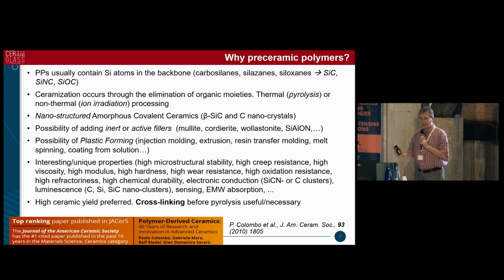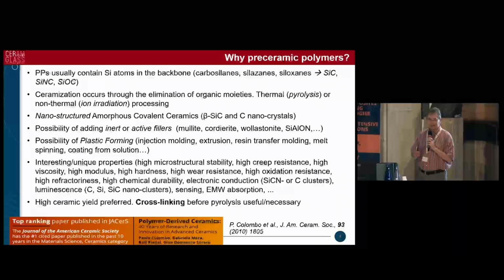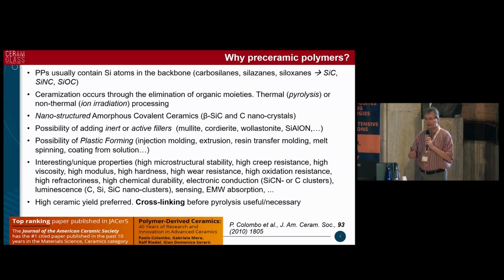On the other side, if you're using a preceramic polymer that has a low ceramic yield, you can still shape it and convert that material to a ceramic component, and the advantage there would be that you increase the resolution of your part. With additive manufacturing technologies, you have physical limitations in terms of the size or the minimum feature that you can generate.